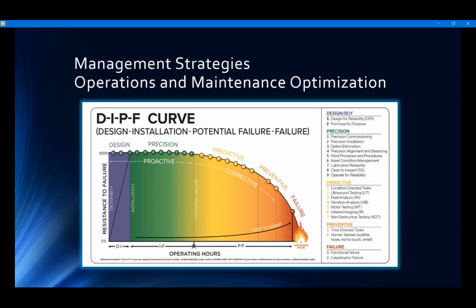Functional failure. Once the equipment enters the functional failure point of the curve, it is no longer producing the results it was designed for. This could be a pump that loses flow and head pressure, or a motor that will trip out on overcurrent. Operational monitoring and repair costs all increase when equipment loses core functionality. Repair costs increase with unplanned downtime, and the time frame to return to service is shortened.